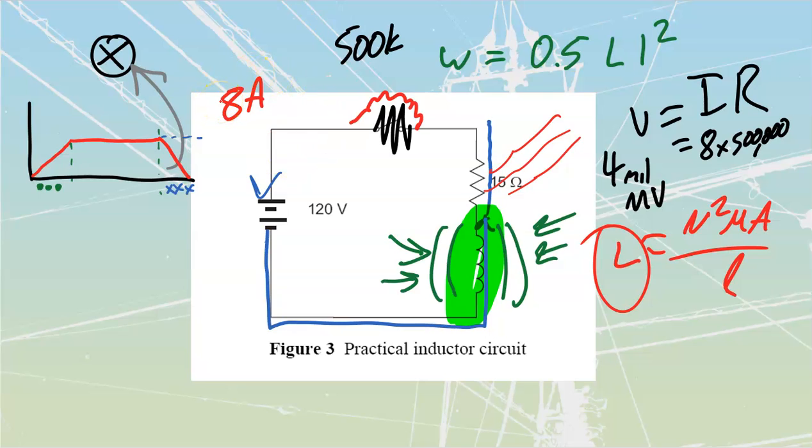It runs out of magnetic lines of flux, right? It's going to have only a certain number of magnetic lines of flux. Once it uses them all up, it's used them all up. It's like a trust fund baby, right? It's got a whole pile of resources, and if it rapidly uses them all up, that's it. It's out. So we're going to have that field over here get pulled back in super, super rapidly. We call this thing inductive kick.